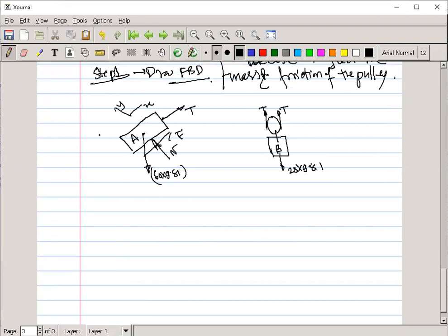Okay, so to solve this type of problem, what you have to do is first check the motion by assuming that they are in static equilibrium, because we do not know from this figure whether they are moving in the downward direction or they are stuck in that position. So first we have to check. For checking purposes, 2T is equal to 196.2, right?